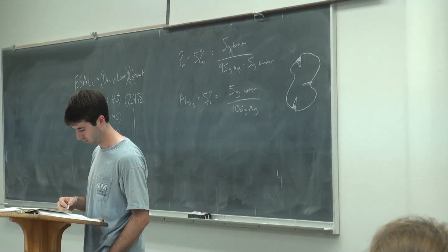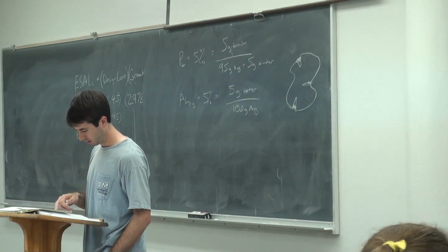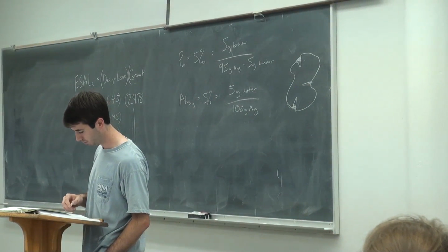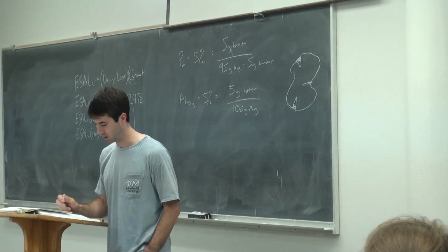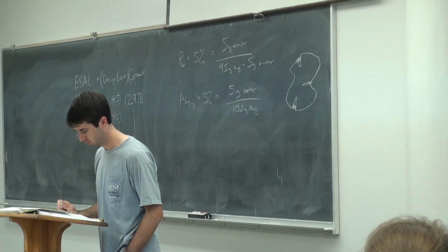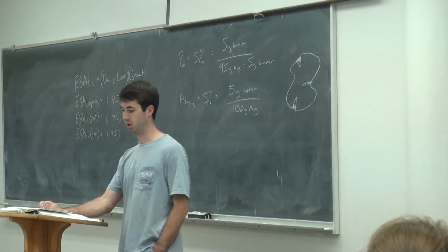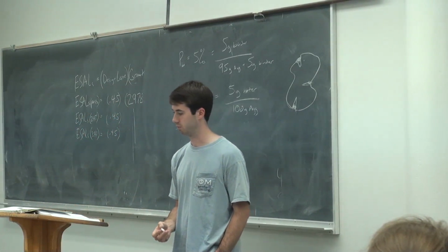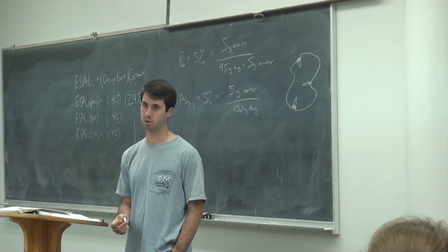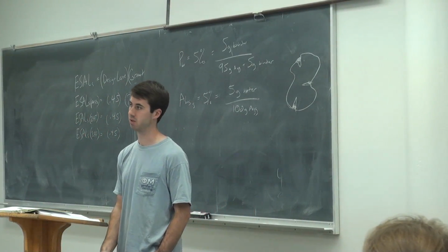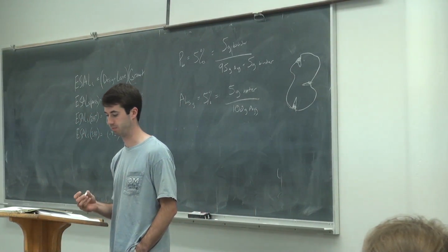When you go to the mixture of asphalt and aggregate, that's typically denoted by the M subscript. And so you've got GMB for the bulk specific gravity of the mixture. You've got GMM for the maximum specific gravity of the mixture, that kind of thing. Any questions on that?